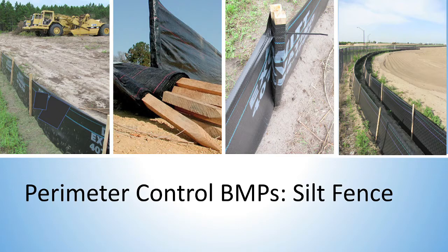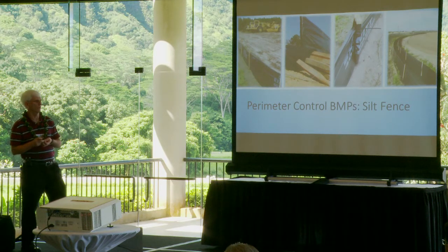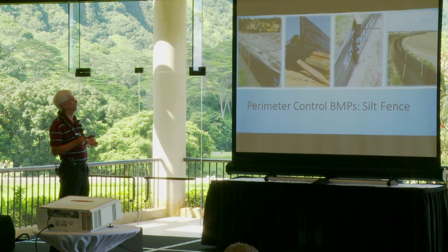So if you have a lot of clay washing off on your site and you're using silt fence, if you don't put some other combination of control on it, it's just kind of like a mile marker post as the muddy water is taking a journey down to wherever else it's headed. You won't really get a lot of control out of that. Most silt fence comes nowadays with either the posts attached or comes in a roll that you install later. You can have wood posts, you can have steel posts, T-posts, etc.